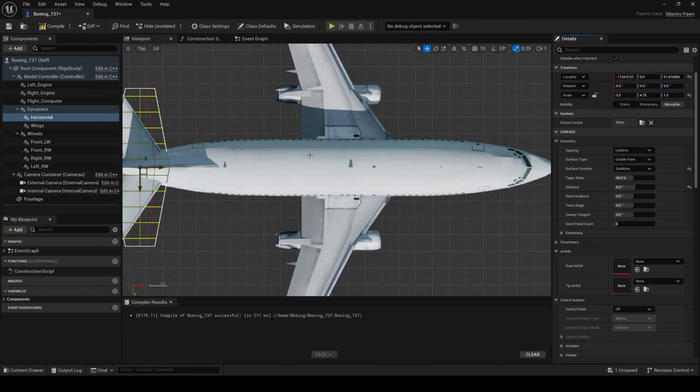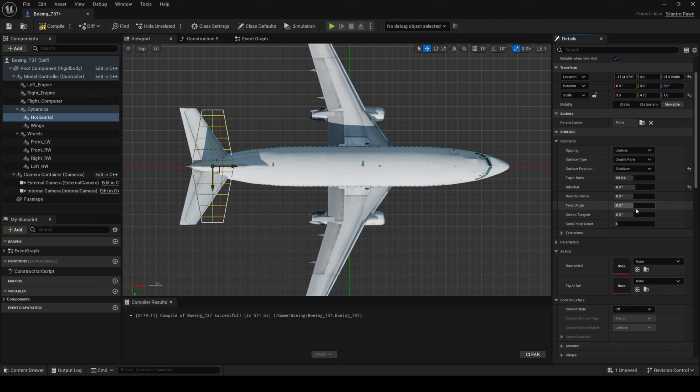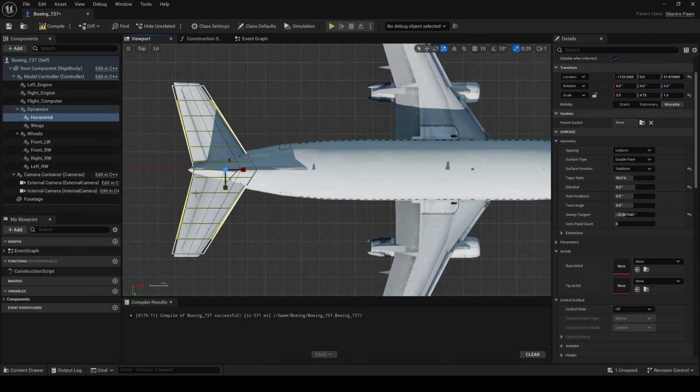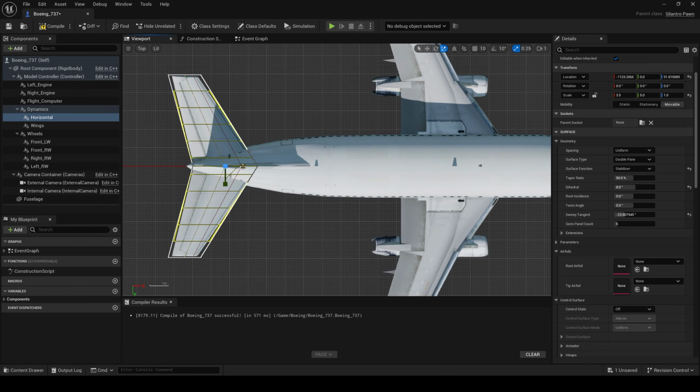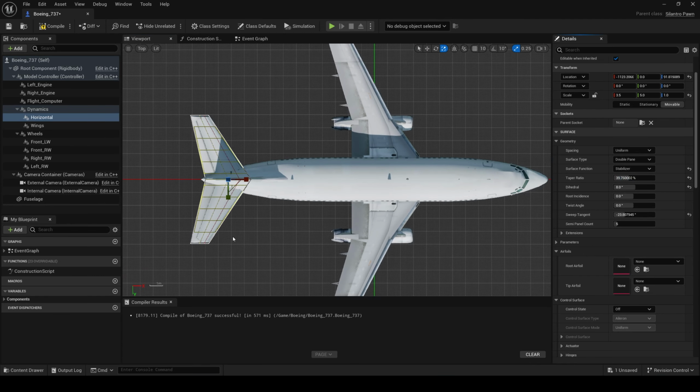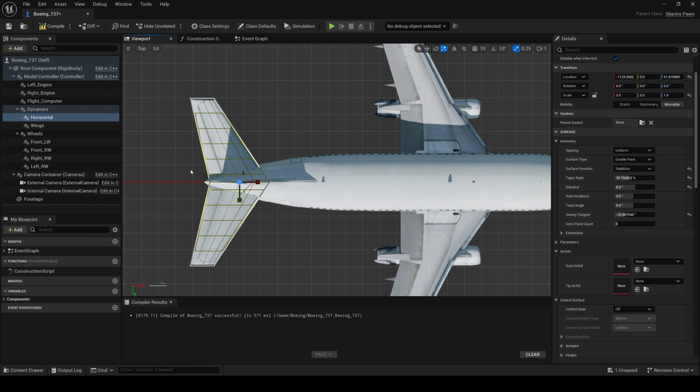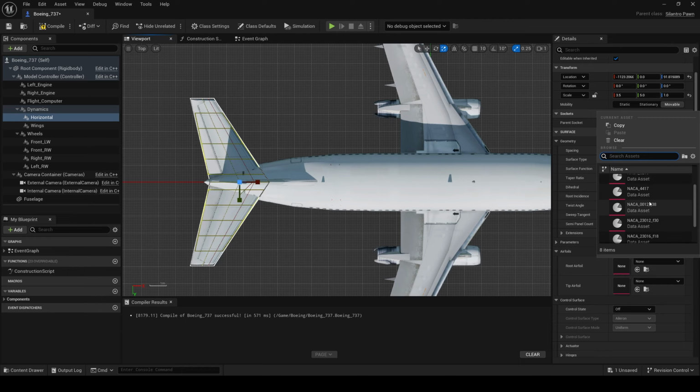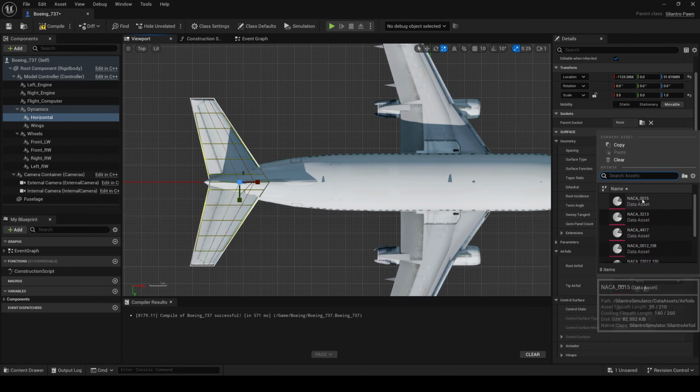And if I switch back to top view, and we sweep the wing backwards, move this forwards a little bit, and then increase the semi-span. All right, that's good. The taper ratio, reduce that. So the other match is really nice. I want to use symmetrical aerofoils on this though, so let's say the 15% one.